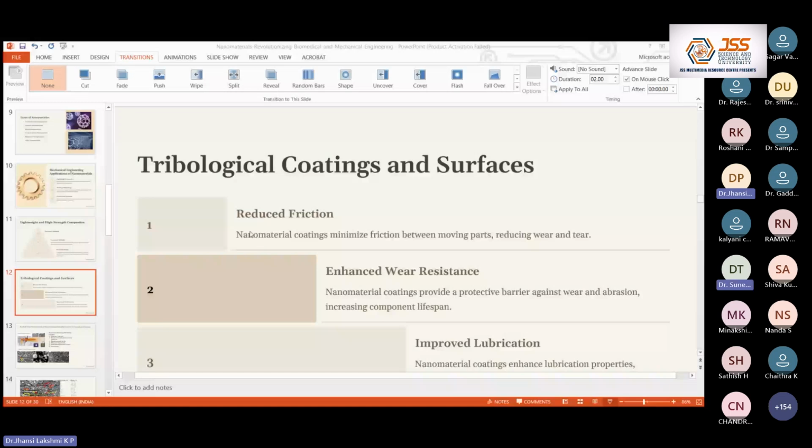In the reinforcement, we are varying the B4C concentrations: 0%, 5, 10, 15, and 20. Like this, the particle concentration is varied. It is observed that for a maximum of 20% B4C, obviously the microhardness is higher for this composition, and the porosity levels are also checked.